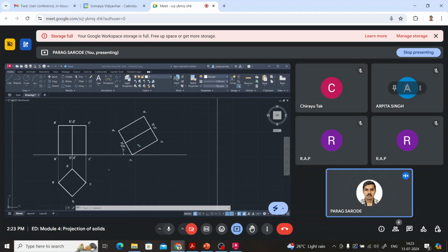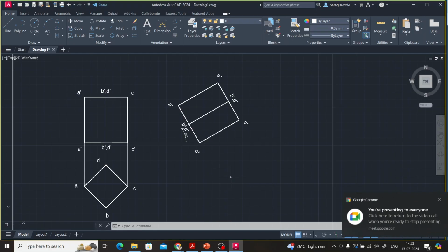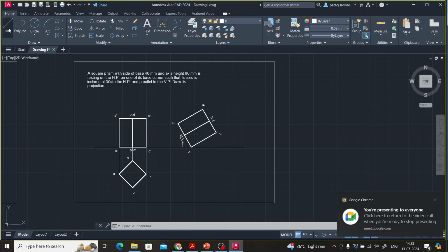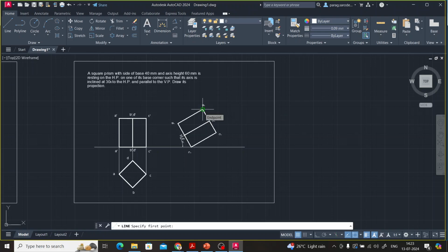So now we will proceed to drawing the projections for the second step. We can see here there are four projections we will get. Not four exactly, two projections for A dash C dash for the top base, and similarly for the bottom base. So we will have to go very carefully and one by one. Okay, so we go here, for the top base B dash D dash, and then finally C dash, correct? Then we draw the horizontal projections from here.